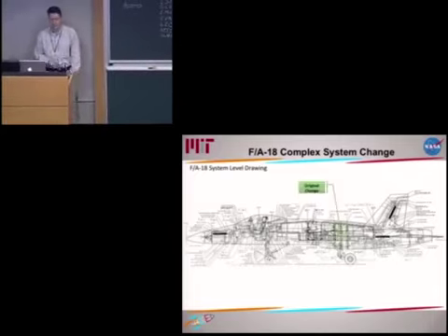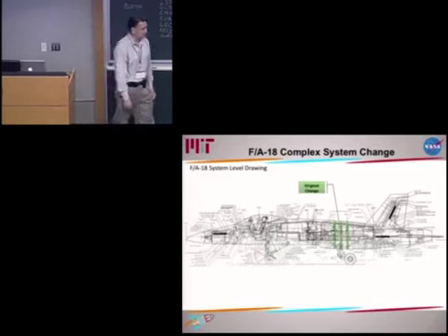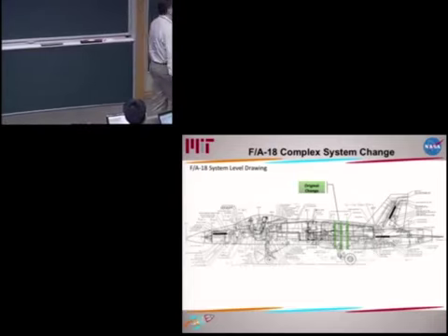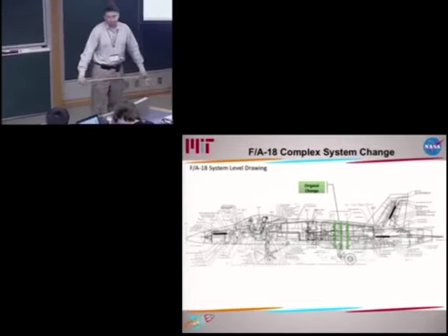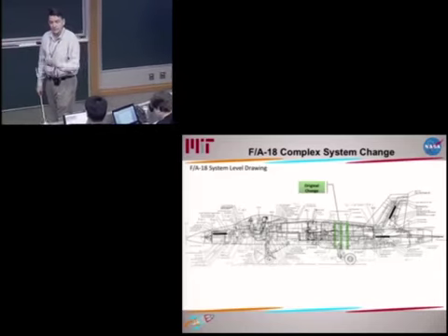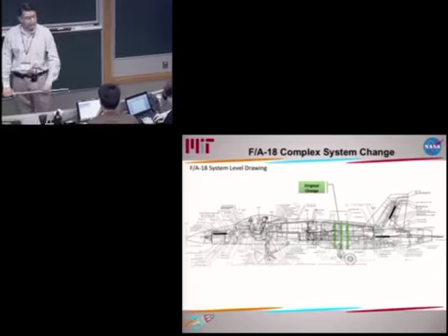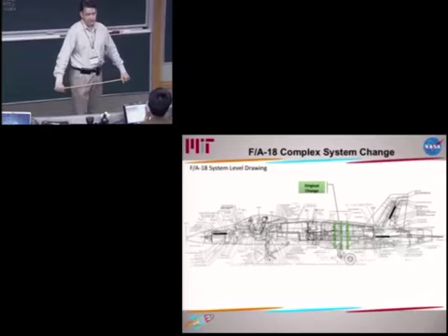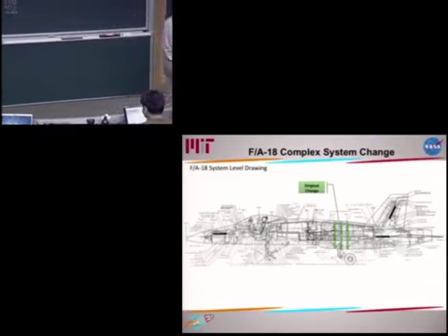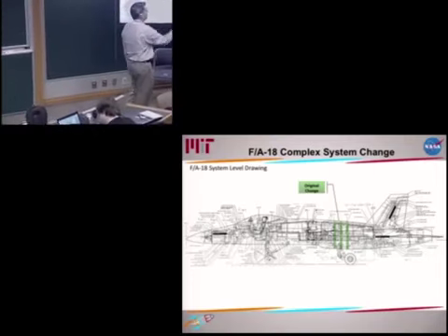And I'll just give you one example of a change that we had to make. That central barrel section of the aircraft that I showed you traditionally had been made out of aluminum. And aluminum is a great material. It has great strength. It's lightweight. It's easy to work with in manufacturing. But it doesn't have great fatigue life properties. So after some analysis, we decided to replace aluminum with titanium, right?